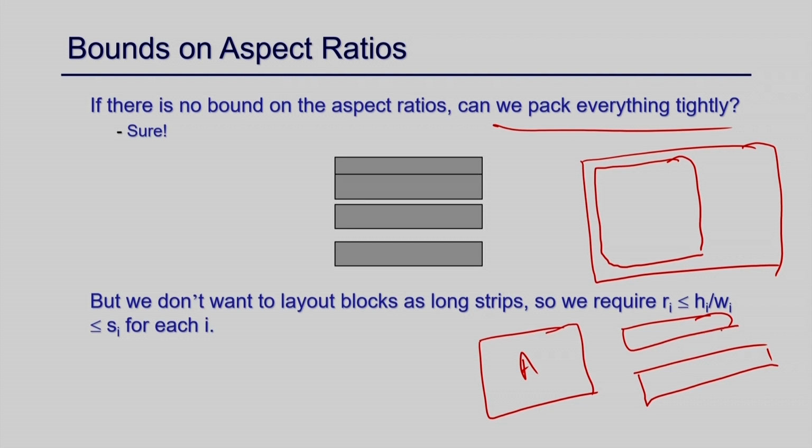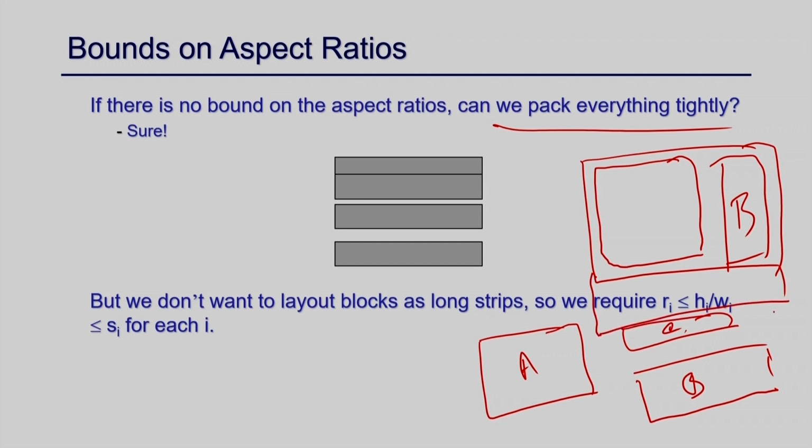Now, suppose this takes the space in such a way that this cannot fit in here and this may not fit in here either. If you place one of them here, their length is more than this, so they cannot be placed this way. So, suppose this is B, I want to place this way, right. Now there is no way to place C because everything is fixed, there is no place. Then you basically have to increase the area of your design, the chip area, just to place this C here, and much space remains vacant, right.